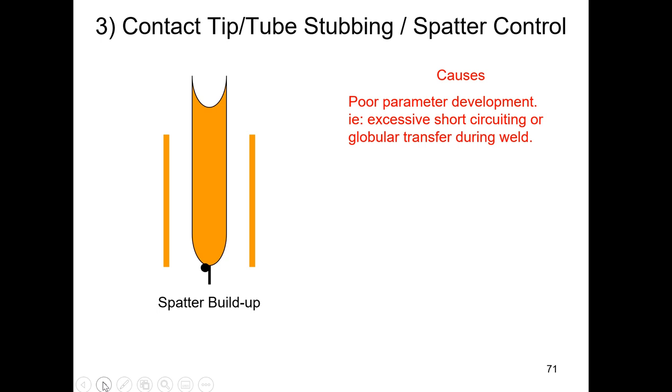Now, I'm deeply suspicious. Notice right in here that there's a bit of spatter stuck right to the edge of the nozzle. Well, that is telltale for me, because the very edge of the orifice is going to be the first area to melt. It's the closest to the plasma, and it's a corner. Corners always melt quicker than a nice large surface that requires more heat input to get it to melt. So when it's right on the corner like that, I have a couple of suspicions that the contact tip itself is overheated.